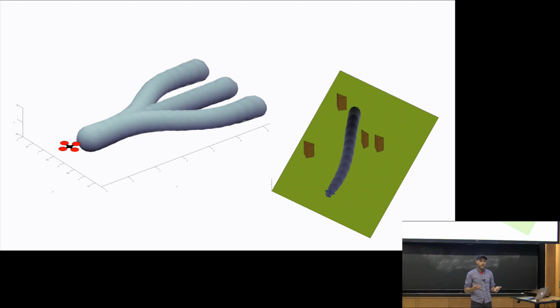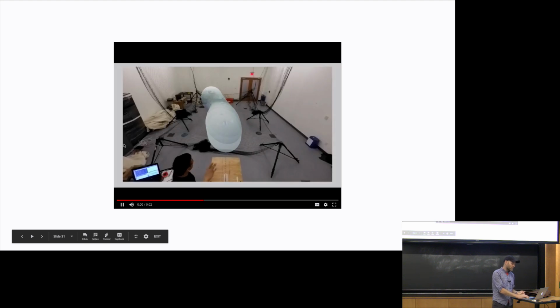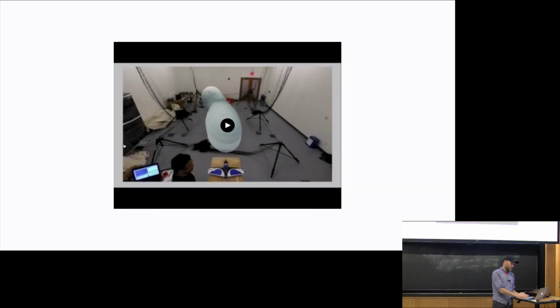Just like for Emilio Frazzoli's controller, I told you about his RRT version where he did the controller by solving value iteration for the helicopter with no obstacles, and used that to do planning when there were new obstacles. Here, the dynamics are known ahead of time, maybe with uncertainty if the wind is blowing, but I can compute those funnels a priori, and then check at runtime if they're a valid certificate. So here's one funnel. Ani worked really hard on that video.